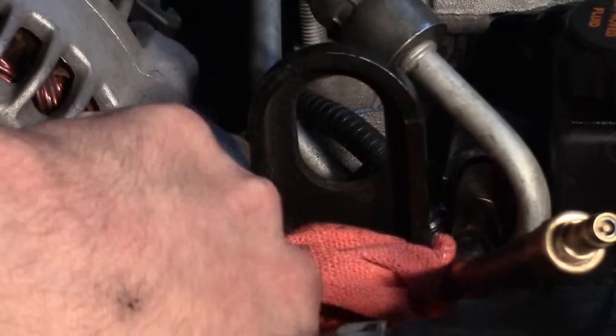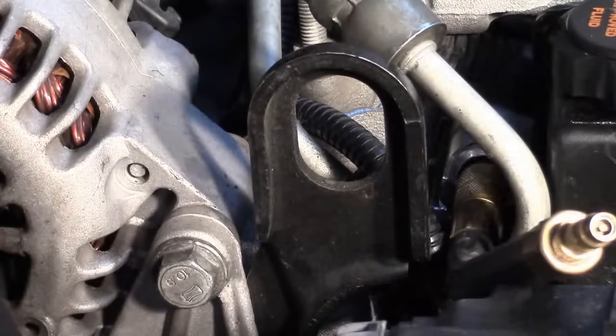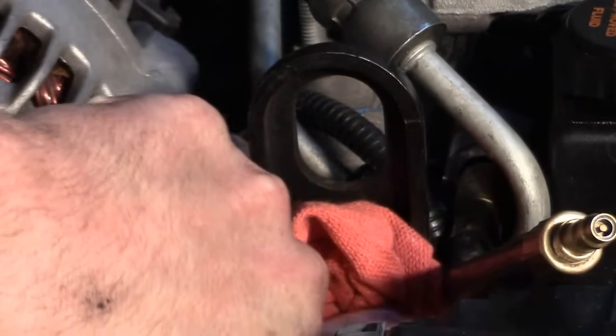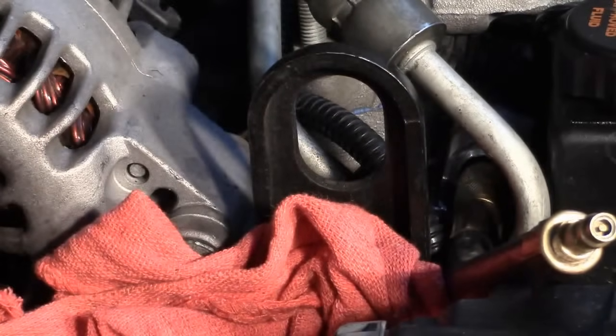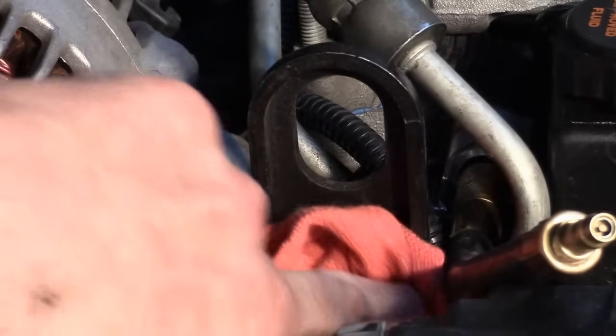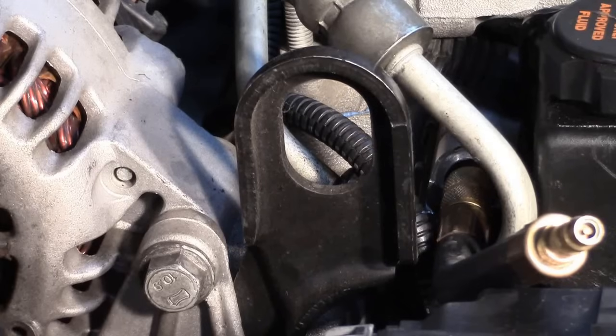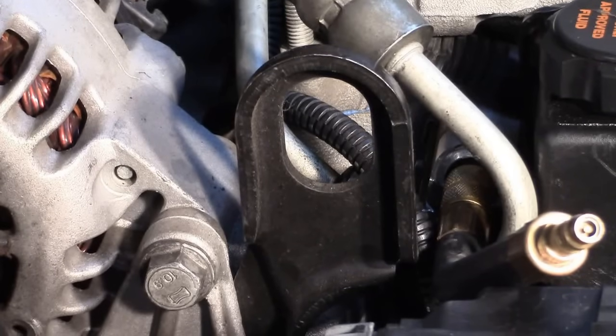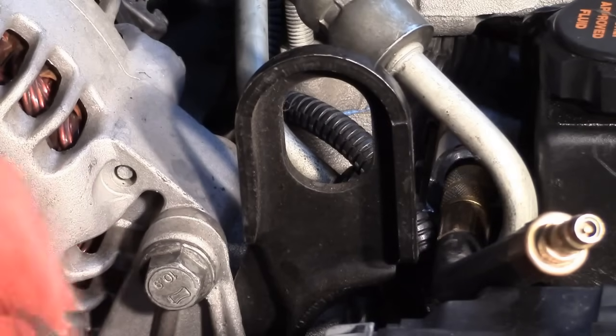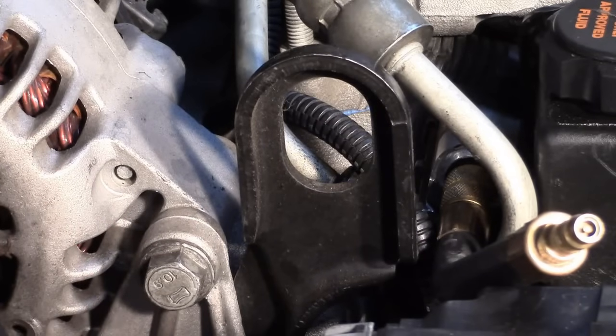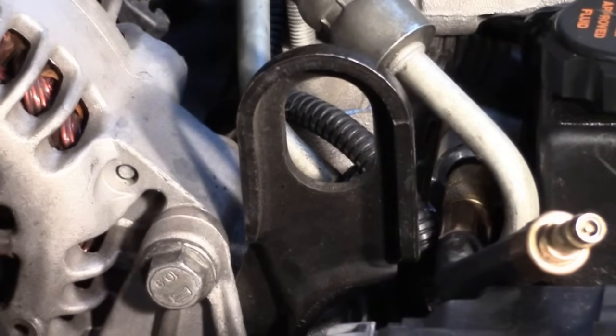Notice I've got a shop rag here so I catch any spilt fuel. You always want to be really safe with that, especially on vehicles that don't have a Schrader valve where I have to rig some connection to tee into the fuel feed or something like that. That definitely can get a little messy. One of the best things to do actually is to just pull the fuel pump relay or something like that on the car to run it dry to relieve the fuel pressure. Typically what I do is I just depress the Schrader valve and just catch the fuel with a rag. That's just fine. But you want to make sure you're not around any open sources of flame and stuff like that if it's winter in your garage heater. But obviously we're doing fuel stuff here, so safety comes first.